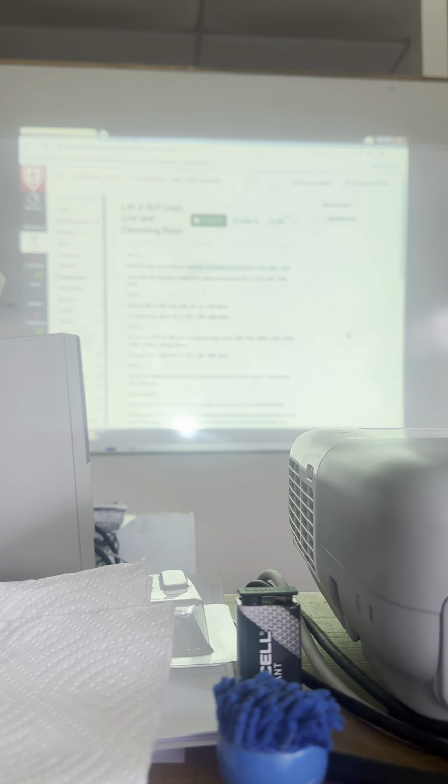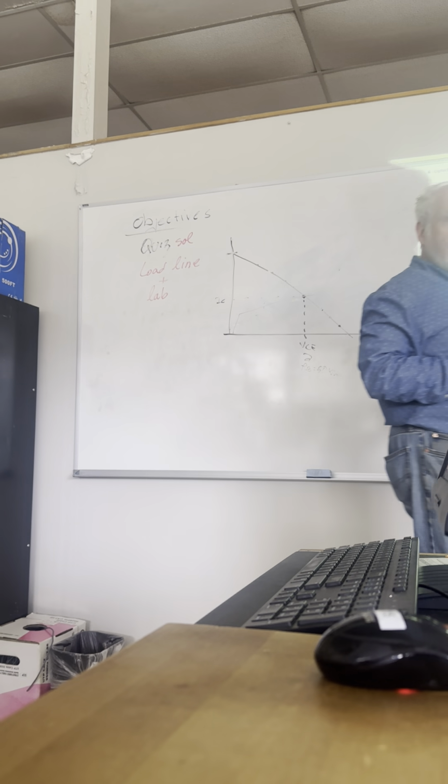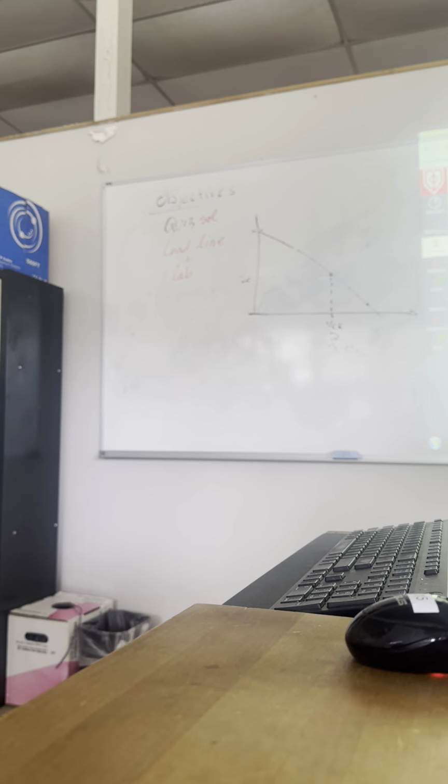The more you increase RB, the more you decrease IB, in other words, the more you decrease IC. You with me so far? The other way around, as I decrease RB versus 50K, I'm going to be increasing IB and hence increasing IC. And notice I didn't touch the 100 ohm on the other side, which means this will be my max point anyway. And didn't touch VCC.